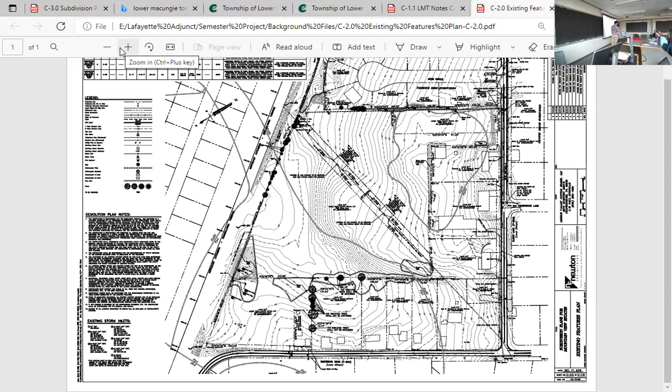Where was I going with that? The soil types tell you the hydrologic soil group, how quickly the water sheds from one spot to another. Now, if I had a spot on here where I had a hatch pattern, and that hatch pattern was the little cattail hatch pattern, what does that mean? Anybody ever see that?